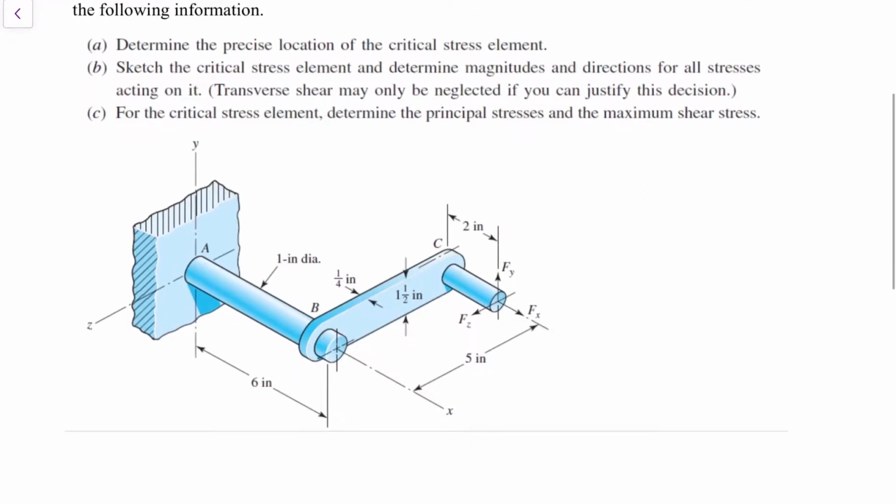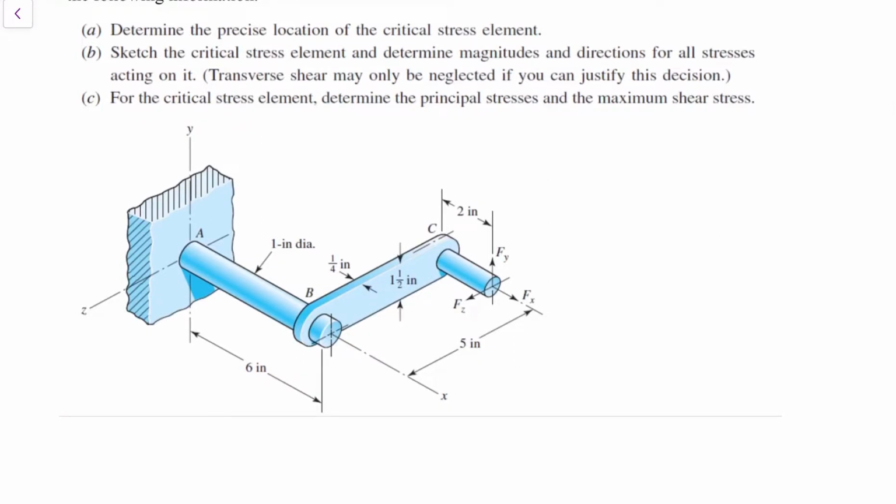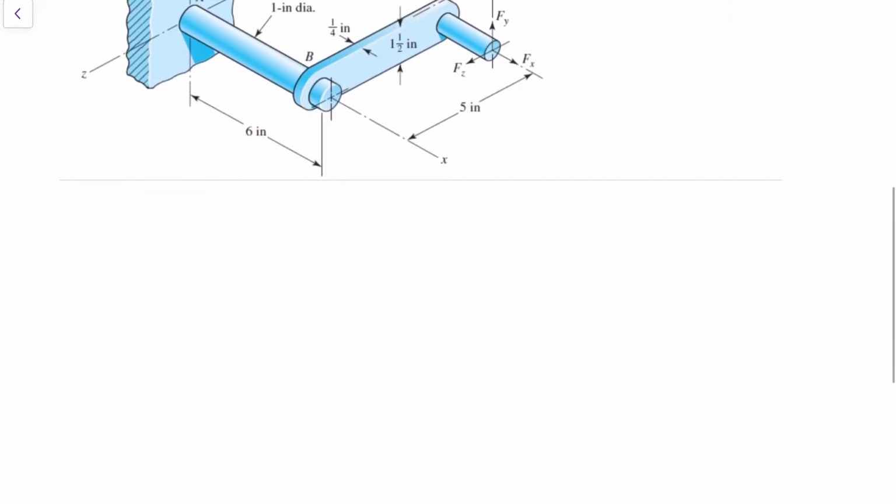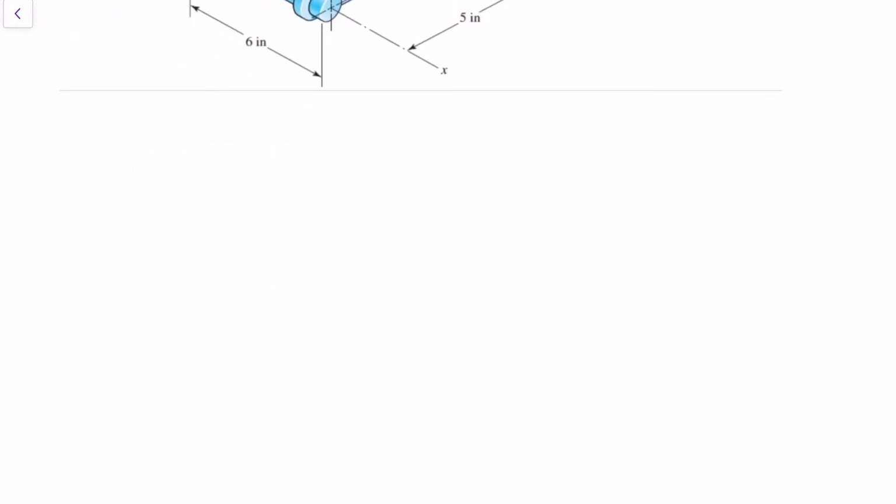So what I'm going to do first is just briefly talk about the stresses and the way I approach the problem. I like to break down a combined loading problem into its separate components and the different stresses, like axial, bending, and then the respective shear stresses, and then solve each one of them individually and then combine them at the end. So first, as you know, we have two kinds of stresses, normal stresses